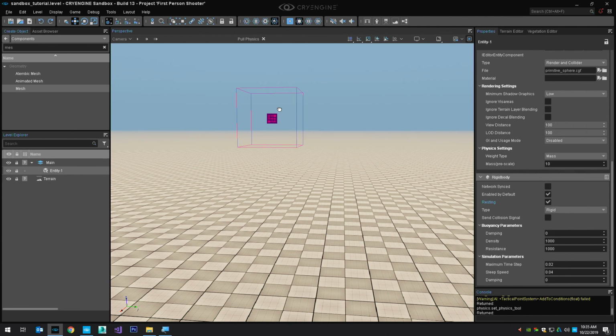By the way, if the ball gets away from you, if you pull it way away, just turn the physics off and turn it on again, it'll go back to its start position. So in other words, what the player does to the objects, moving the objects in the game, is not permanent. We're not changing its position permanently. Really important that you remember, turn off the physics preview. Don't modify your world. Don't modify entity properties with the physics running, because often that is temporary.